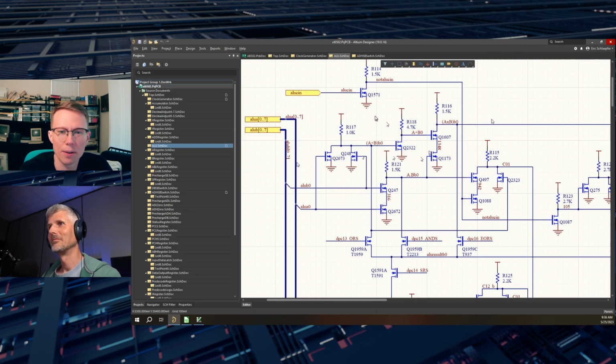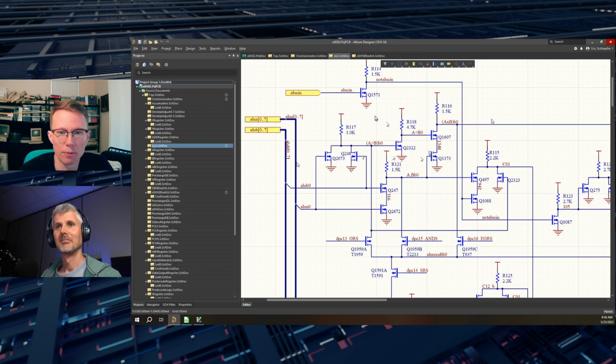Yeah, and even in the 70s, this would not have been typical. If you look at the original 6502 schematic, which I've seen, and you could find similar ones out there, it's not like it's that hard to find. People have digitized some of the mask licensees' schematics, which are similar. What they'll do is they'll draw individual gates. They'll draw inverters using the standard logic symbols, as you're accustomed to seeing. Few devices are drawn differently.